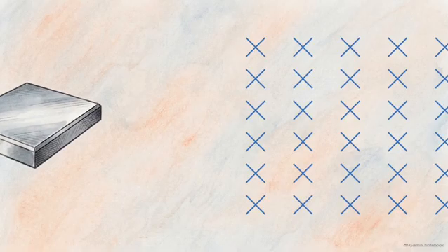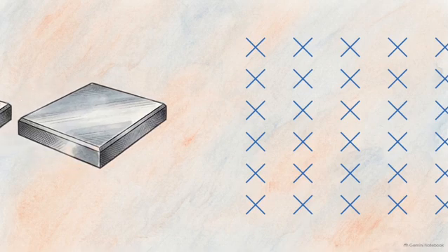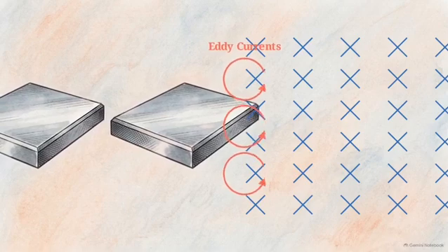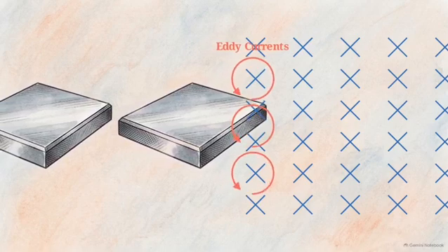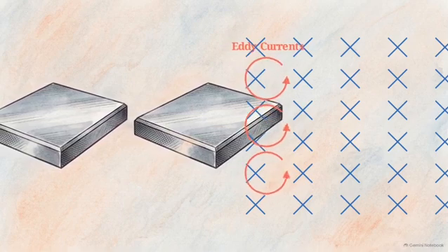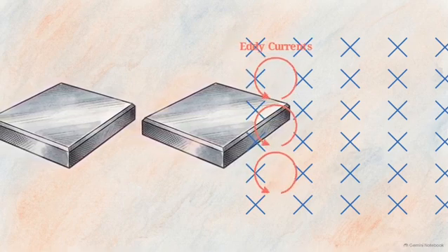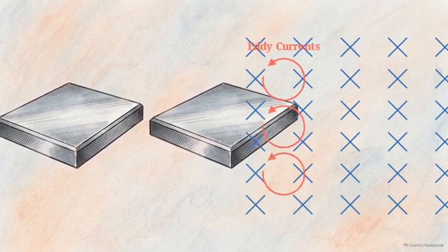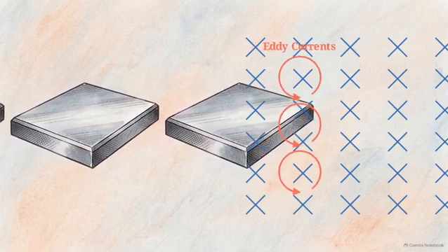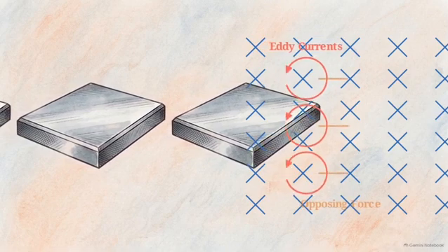Isolating this interaction in a 2D cross-section makes the internal forces clearer. Swirling loops of electrical energy only materialize at the interface line. Metal crossing the boundary experiences a massive flux change, while the interior, where the field is constant, remains inert. What happens next is governed by Lenz's law. An induced current always flows in a direction opposing the change that created it.